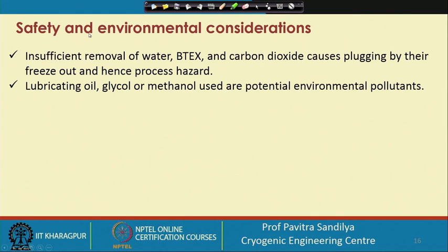And there are some safety and environmental considerations. Even though this process is not that hazardous, there may be insufficient removal of water and BTEX, that is benzene, ethyl benzene, toluene and xylene, and carbon dioxide, which may cause plugging by their freeze out and hence process hazards.